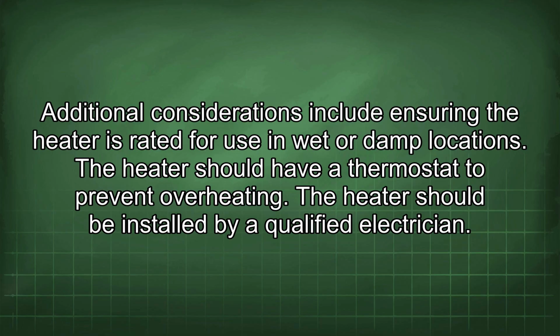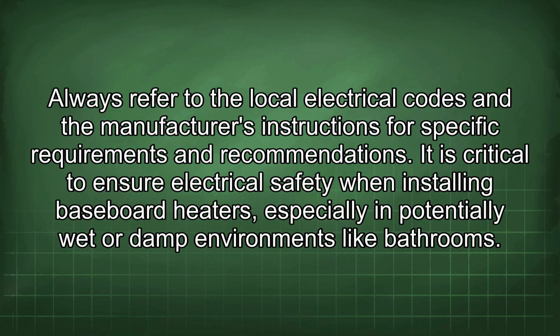Additional considerations include ensuring the heater is rated for use in wet or damp locations. The heater should have a thermostat to prevent overheating. The heater should be installed by a qualified electrician. Always refer to the local electrical codes and the manufacturer's instructions for specific requirements and recommendations. It is critical to ensure electrical safety when installing baseboard heaters, especially in potentially wet or damp environments like bathrooms.